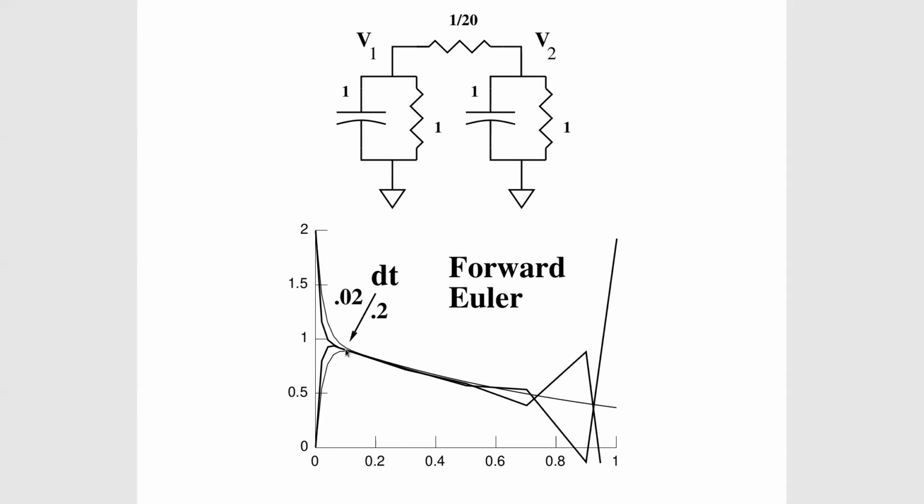Now, if we wanted to achieve some computational efficiency, we might think, well, things are moving very, very fast here, so we needed a fast time step. But when they start to move very slowly, maybe we can get along with a longer time step. So let's make dt be 0.2 of a millisecond, 10 times longer. Okay? And so now our solution can zip along much more quickly, except that we eventually start to see oscillations in the solution. And the oscillations are getting bigger and bigger at every new step until we get these massive overshoots and the solution blows up.